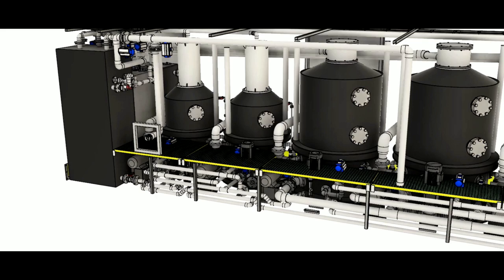That secondary fractionate then goes to the light grey tank in the centre, where it's held until a certain volume builds up. And then using the left-hand side fractionator, we're able to conduct a tertiary fractionation step. We've been doing a lot of work in the last 4 weeks or so on tertiary fractionation, and we're able to get between 200 and 500 times concentration step there. So all up, we're now north of 1 million times concentration factor, just using air bubbles. No chemicals whatsoever in the process. There's no absorbent medium or IX resins or anything. We're just using air bubbles to create these phenomenal levels of separation.